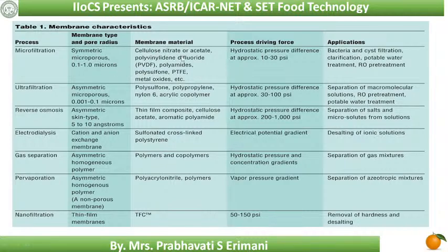The membrane materials are cellulose nitrate, acetate, polyvinylidene difluoride (PVDF), polyamides, polysulfone, PTFE, metal oxide, etc. The driving force is a hydrostatic pressure difference of about 10 to 30 psi, and the applications are bacteria and cyst filtration, clarification, potable water treatment, and reverse osmosis pre-treatment.